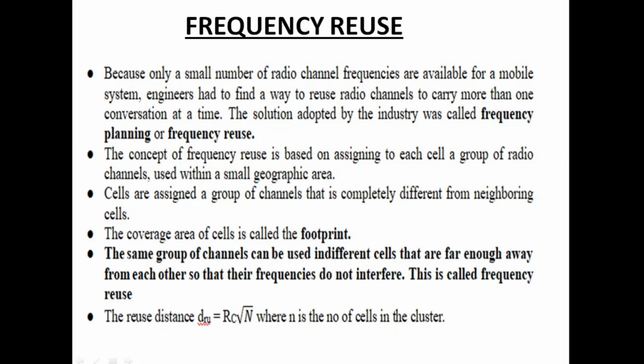interference. Using this concept, it is only possible to accommodate 40 users in a frequency band of 1 MHz and 4000 users in a frequency band of 100 MHz wide. Today, cellular systems have millions of subscribers, and therefore a far more efficient method of using the available spectrum is needed. The method that is employed is to enable frequencies to be reused.